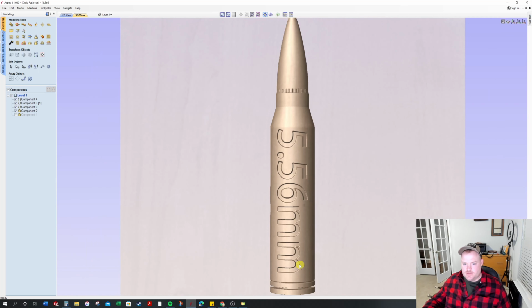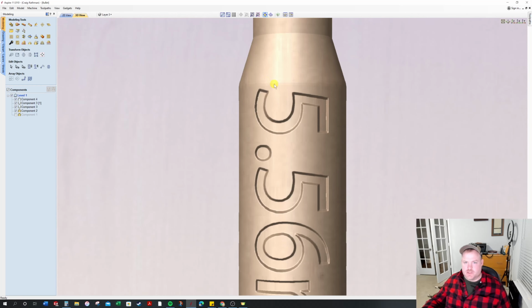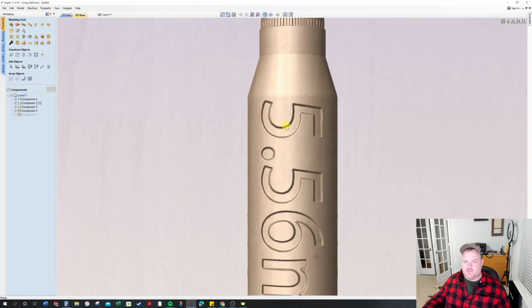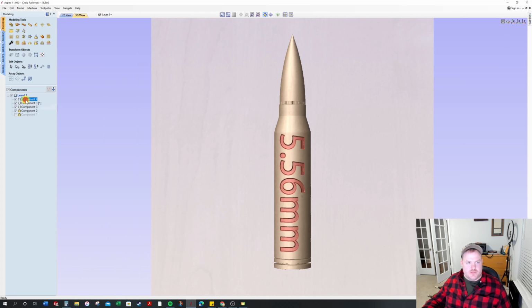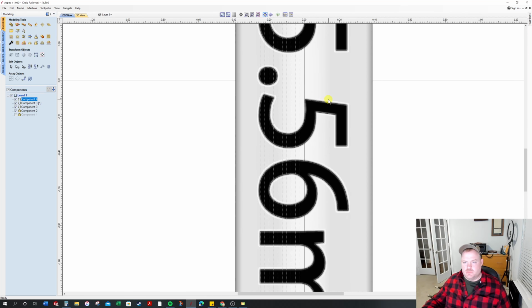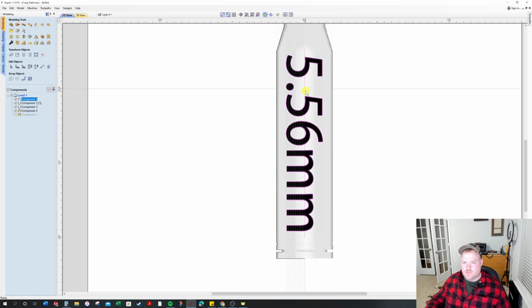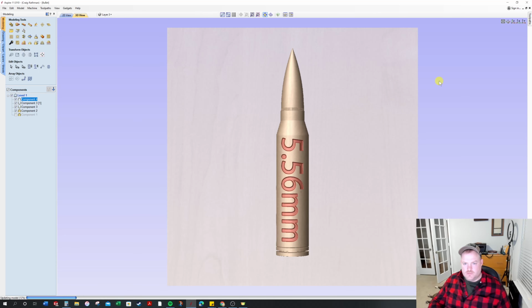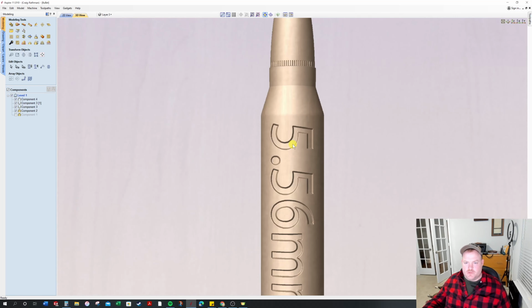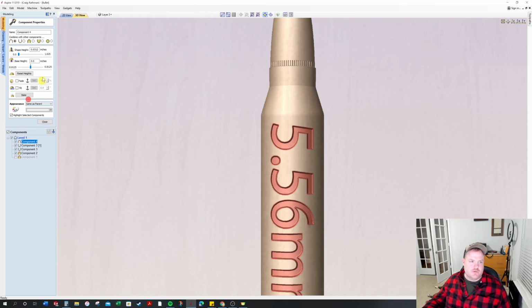And you can probably pull down the lettering here because it's still kind of close to this edge here for me. And you could easily do that while it's created. You could even do it in the 3D view. And the other thing you can do is you can click on it again, open up the properties, and you could set that height deeper if you wanted.